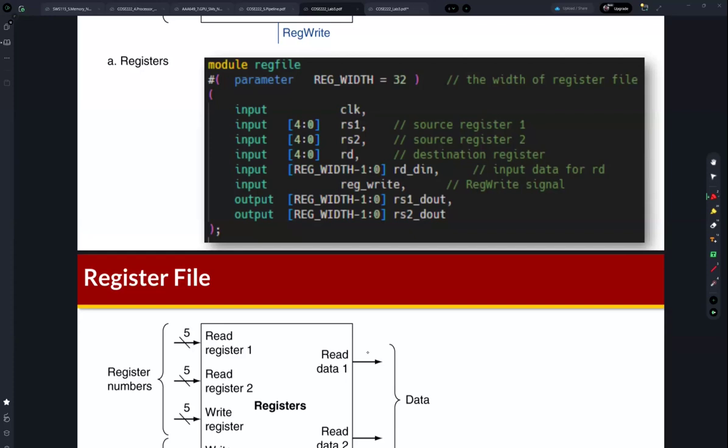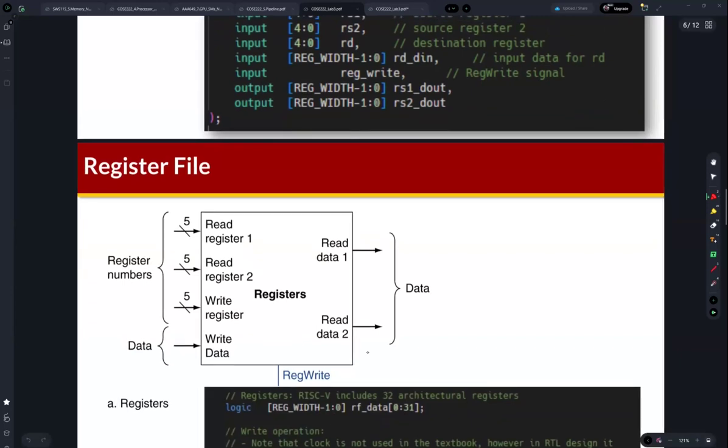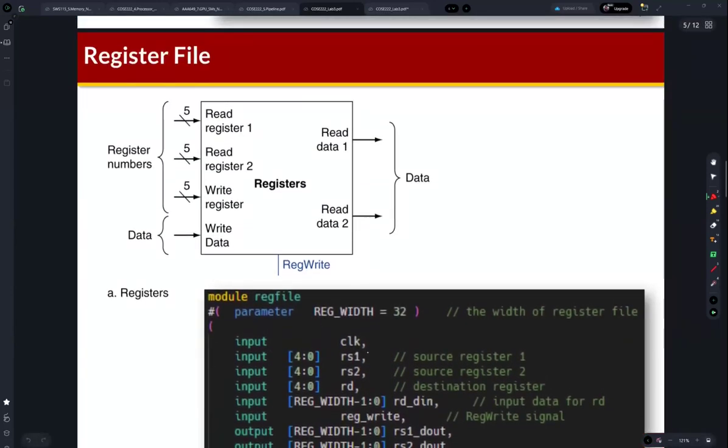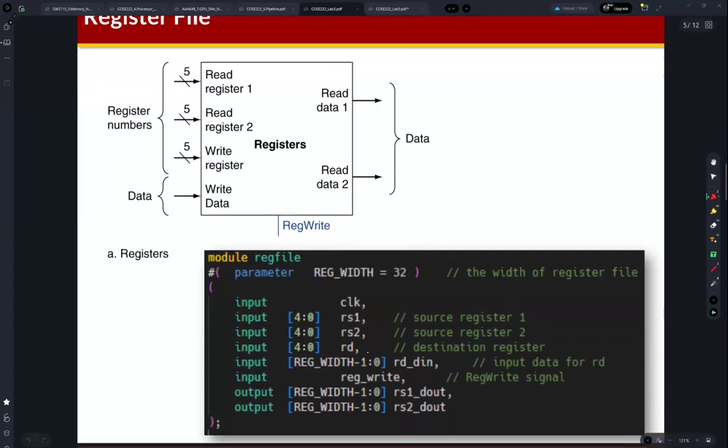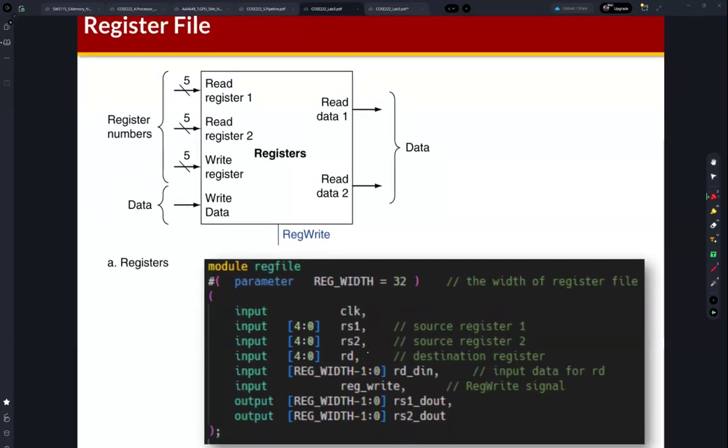So we can write the test bench using C++ code, and using this C++ test bench code, compile the converted source files, generate the binary file, and then execute this binary file.